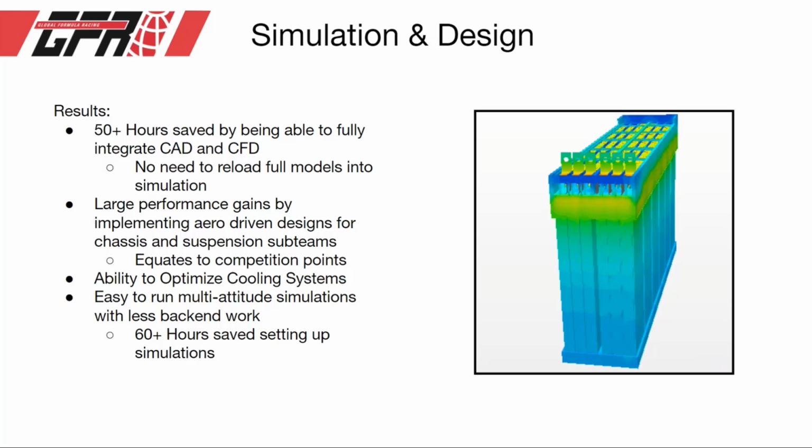CFD simulations allow GFR to gain more competition points by increasing vehicle performance through aero-driven designs intended to increase downforce and reduce drag. The use of StarCCM Plus gives our team a greater understanding of airflow around heat-generated components so that we can meet our cooling requirements.